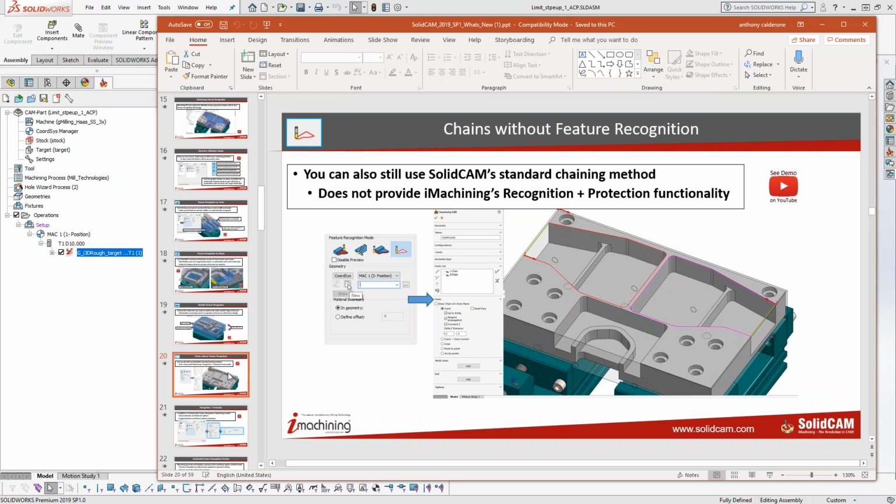So in the old 2D iMachining, it doesn't look at the target. It just looks at the chain. You can apply negative and positive offsets to it, and you can just cut. So we have the existing iMachining 2D. You can just fall back on at any point. So we're not removing the way the software worked in previous versions. We've just extended it for new features.